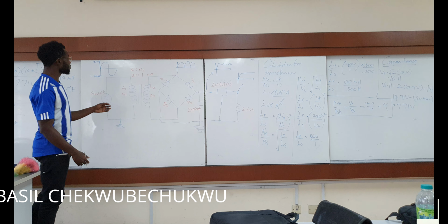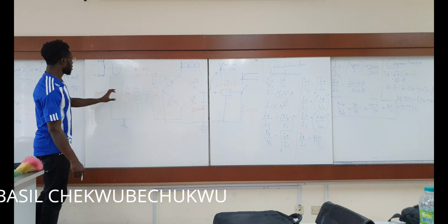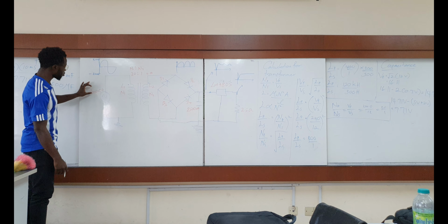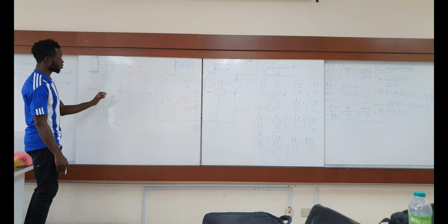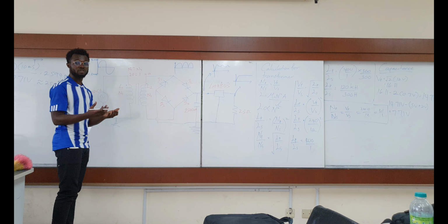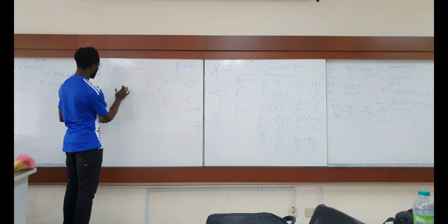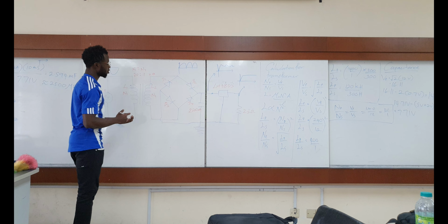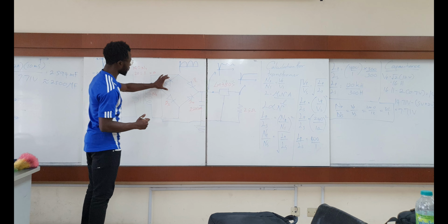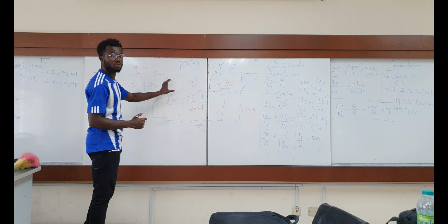Okay, I'm going to explain briefly how the circuit diagram works. Here we use a 240 volts input, so we need a step-down transformer. We use a 12 volts step-down transformer. After this transformer, we have a bridge rectifier with 4 diodes.